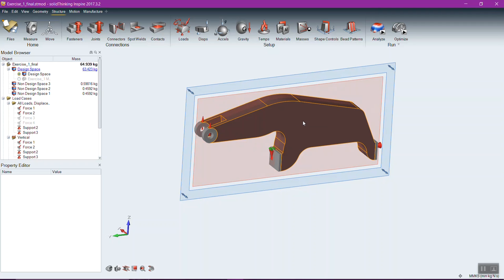We segregate design and non-design space because in the case of this part, it's evident that some sort of rod is going to be going through the end here, and it's going to be mounting in some way to something here. So we need material there. We need a nice hole to be there, and we need a nice flat area to mount. We separate those out as non-design space, the region that the solver can't touch. But the big red area, the solver will carve away at that. It will determine what material is necessary and what material is not necessary.